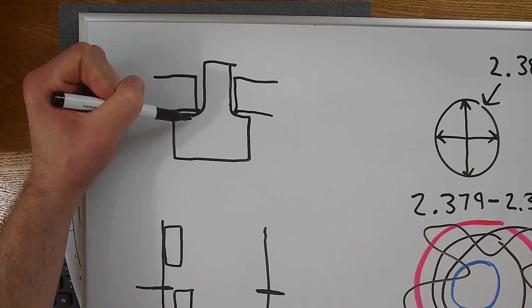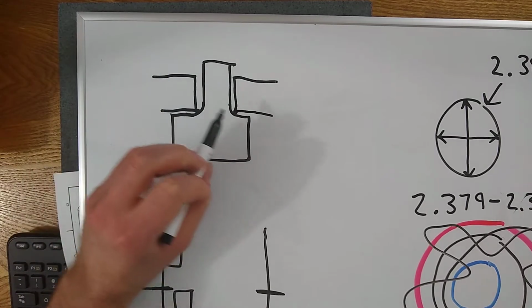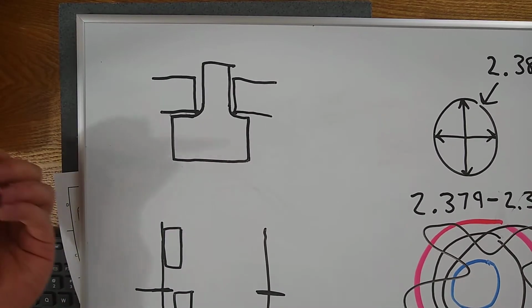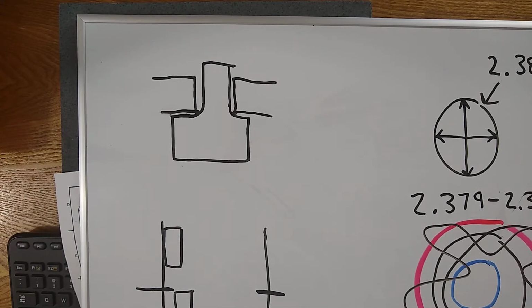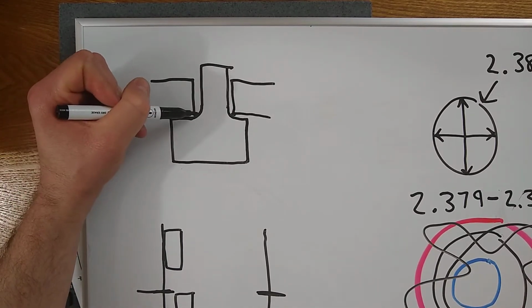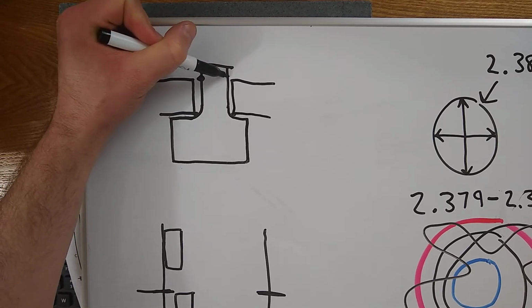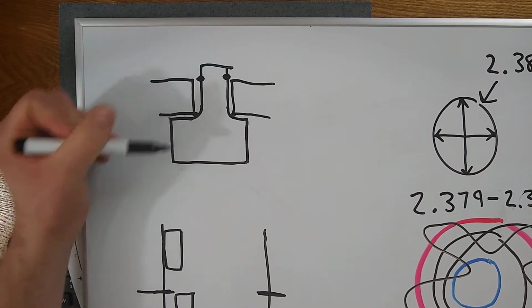This is a tightly controlled feature usually, and it might just be in the title block. I think it's in the title block of our example. Max radius 30 thousandths, but you'll want to get your impact points actually away from the radius.